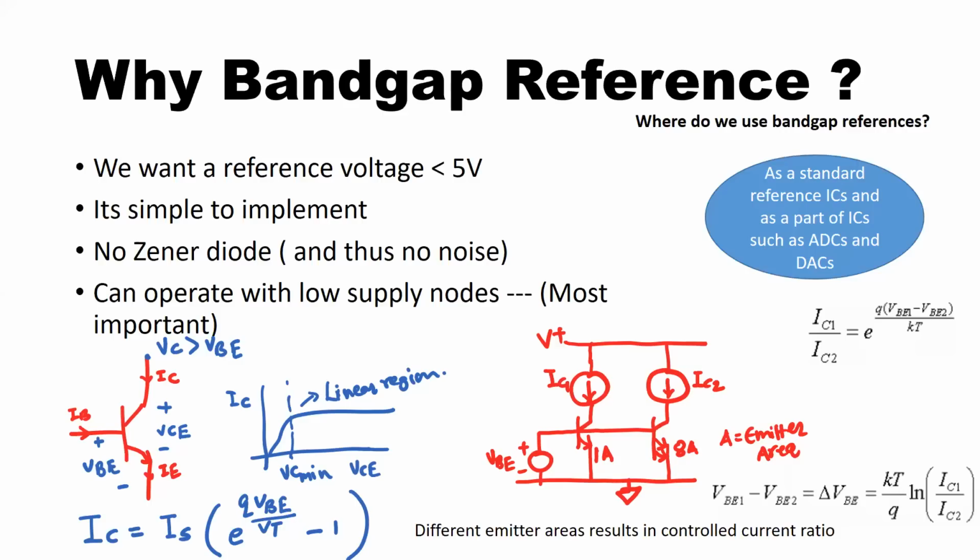Hello there, welcome back to our discussion on the voltage and current references. In our previous talk, we discussed how to generate a current reference which is independent of the temperature variation. So we generated a current with the positive temperature coefficient, and a current with the negative temperature coefficient, and we added them together to generate a current which was independent of temperature variations to the first order.